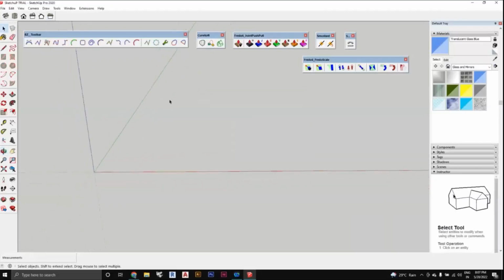So the first tool that I am gonna teach is known as the Bezier toolbar. In this, all do the same job, but the most important one is F Spline, and I will be teaching this for you. The F Spline has the same function as the spline tool in AutoCAD.